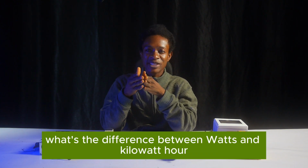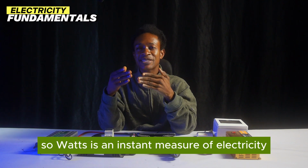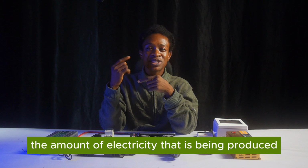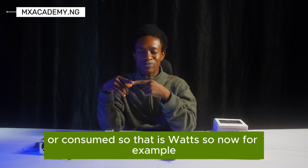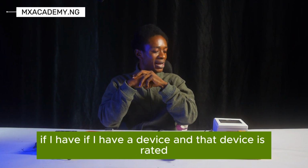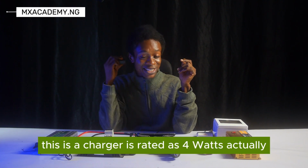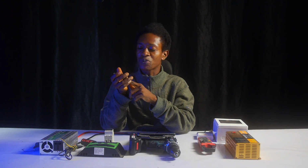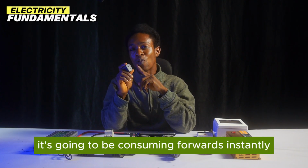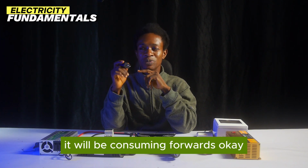So what's the difference between watts and kilowatt hour? Watt is an instant measure of the amount of electricity that is being produced or consumed. For example, let me use this charger, which is rated at 4 watts. What it means is that if I plug in this charger, it's going to be consuming 4 watts instantly and continuously.